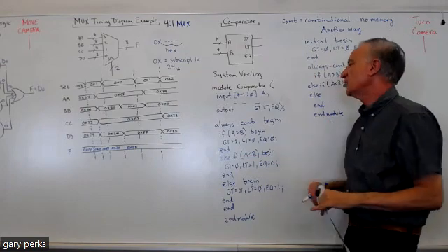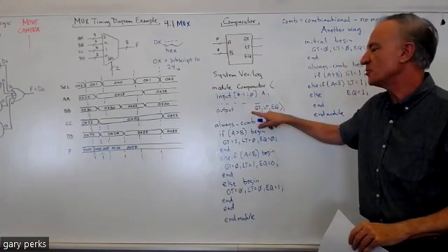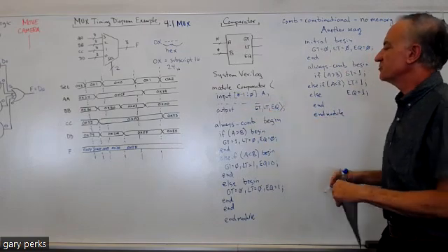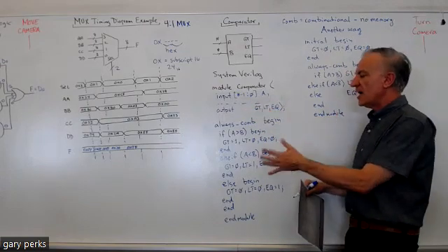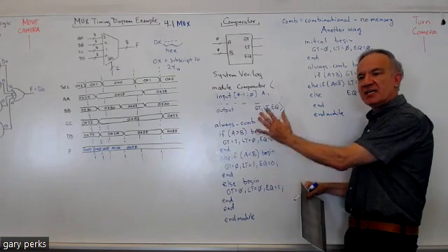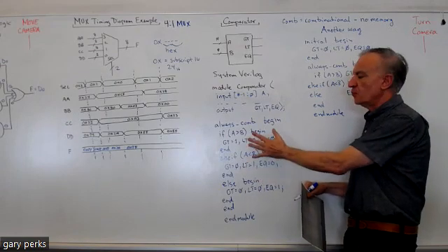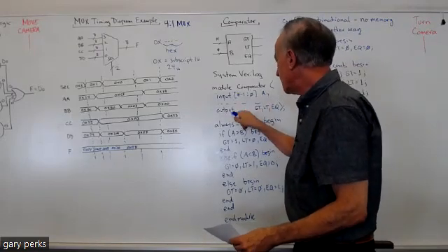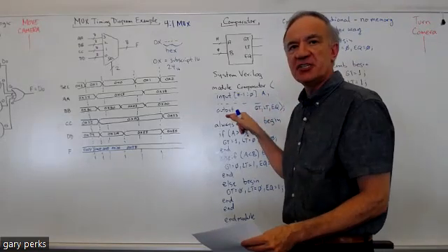Oh, I almost forgot. I've got to come back to this, right? Remember I said I left the space here for a reason? When you have an output or outputs within an always_comb, you can't just put output and then the names like you've been doing.